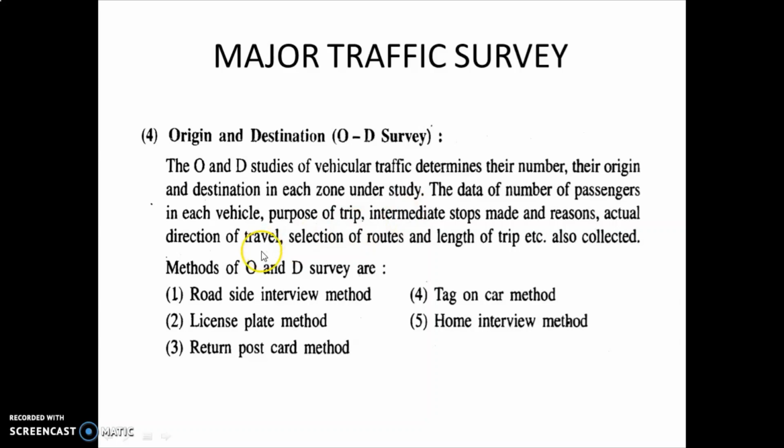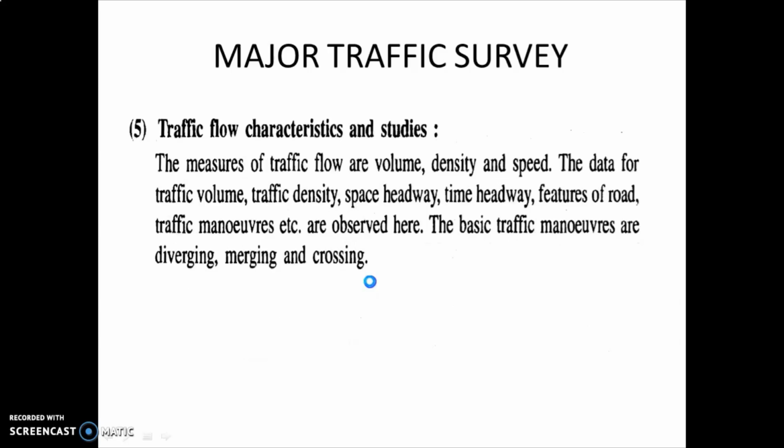In that, again there are so many methods. The methods of O and D survey are: first one is the roadside interview method, the license plate method, the written postcard method, the tag-on-car method, and the home interview method. So again, here five methods are there, which you can use to collect the data.